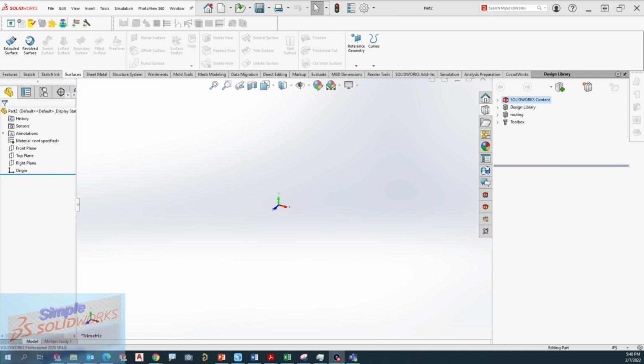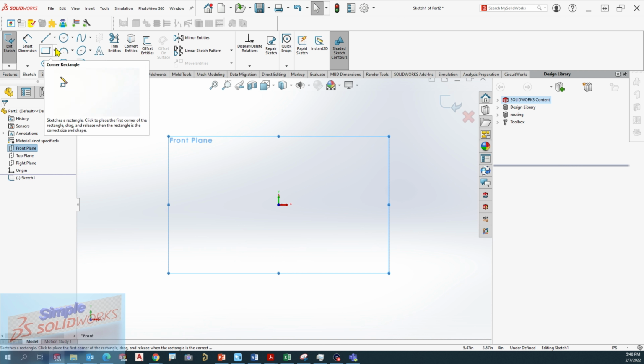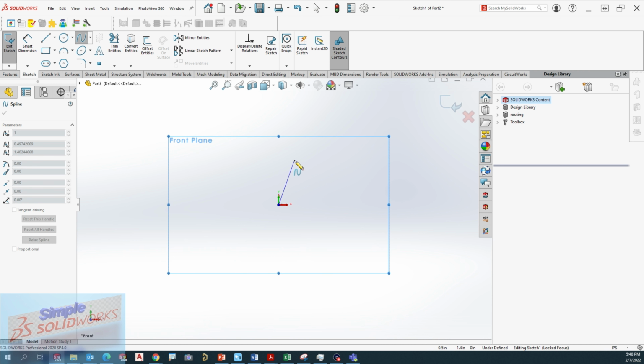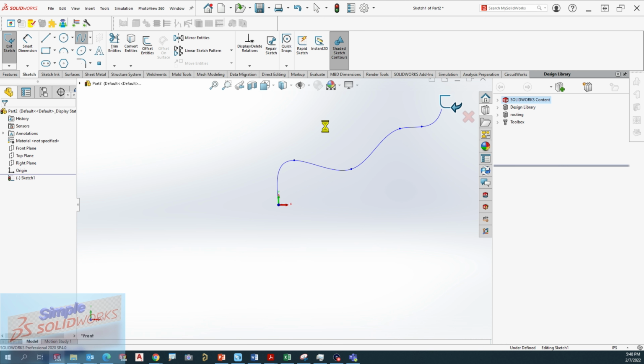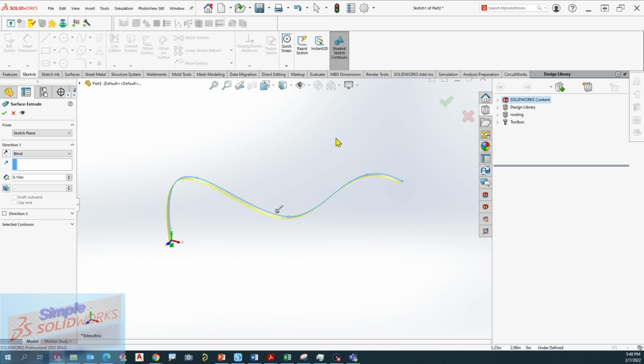So first of all, we're going to start with the extrude. We're going to first select the front plane here so we can create a quick sketch. Let's say one of these, this one right here. I kind of like doing that. I'm going to create a quick sketch. If this thing wants to activate eventually, there it is. I'm going to create something weird like so, and then hopefully, when this thing stops thinking for a minute, we're going to have an extrusion.